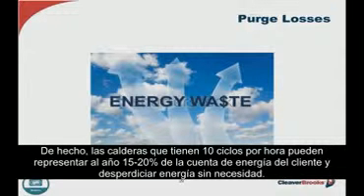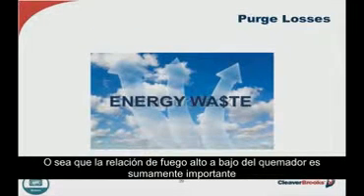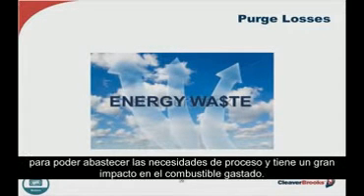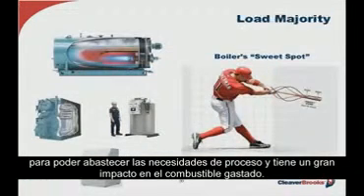And as a matter of fact, boilers which cycle inordinately, let's say 10 times an hour or more, can easily cost the customer 15 to 20% of their fuel bill per year in needless energy waste. So burner turn down becomes extremely important in meeting the process needs, as well as significantly impacting the fuel spend.